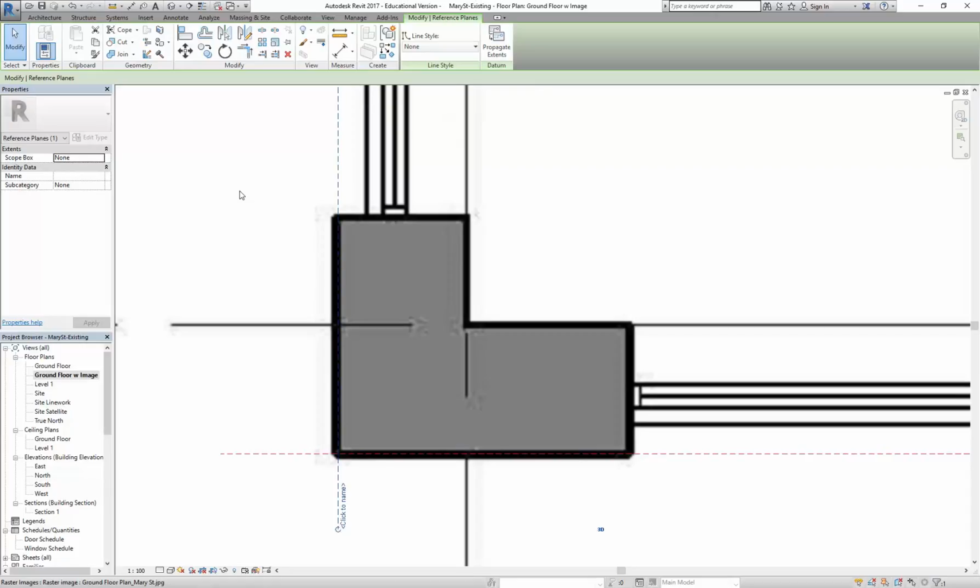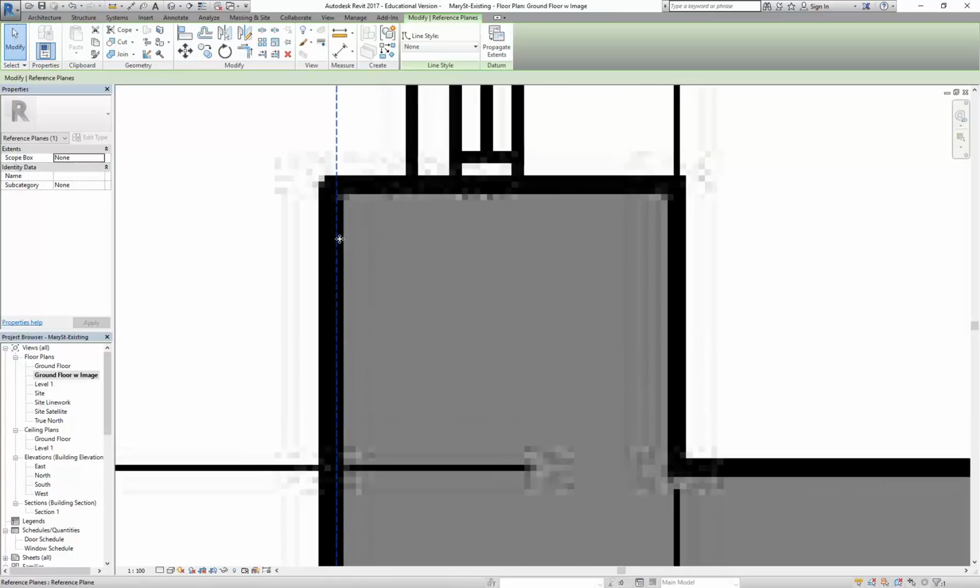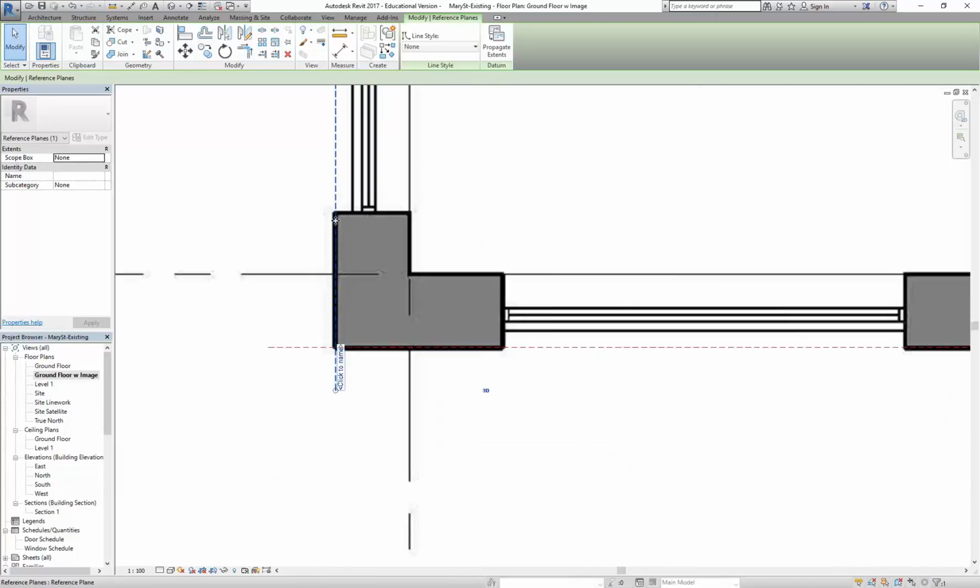A lot of hand drawings, though, for external or things that are cut, like a wall particularly, they would actually put the line weight inside. So the edge of the line was where you should be measuring from. With older hand-drawn, beautifully drawn architectural drawings, it's actually the outside of the line you should be measuring from. Which I know logically in some ways doesn't make sense, but that's the way they did all their drawings. All architectural drawings up until about the 1980s were done that way, with the line weight inside. So here, that thick line would have been entirely inside the wall, and the edge of the line would have been the outside of the wall. But with computer drawings, it's the center of the line.